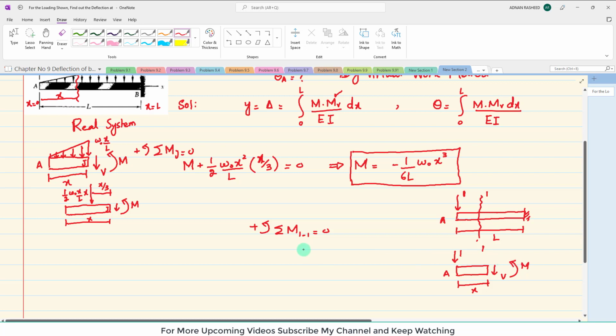There is a moment M that is positive because it is counterclockwise, and the unit load again produces a counterclockwise moment, equal to the load multiplied by the perpendicular distance, that is plus 1 into x. Their sum must be equal to 0. It means this moment will be equal to minus x. Now this moment is the virtual moment, and I will write it as mv.